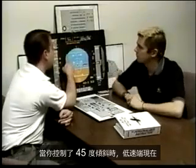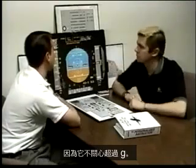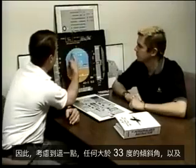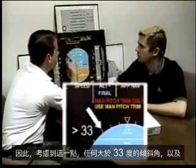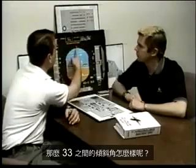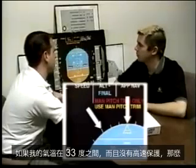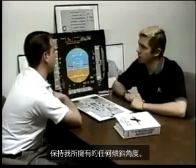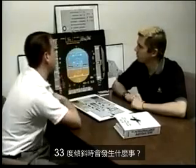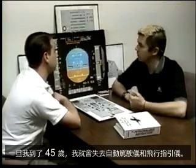What about on the low speed end when you've commanded 45 degrees bank and now you let go of the stick? In low speed protection, it's just going to roll back to 33 degrees because it's not concerned about the over-G. So with that in mind, any bank angle greater than 33 and you let go of the side stick, what occurs? It's going to roll to at least 33 degrees. What about a bank angle between 0 and 33? If I'm between 0 and 33 degrees and I'm not in high speed protection, it's going to maintain whatever bank angle I have. Anything that might occur at 33 degrees bank and beyond? Beyond 33 degrees bank, I'm going to lose auto pitch trim. And once I get to 45 degrees, I'm going to lose the autopilots and the flight directors.